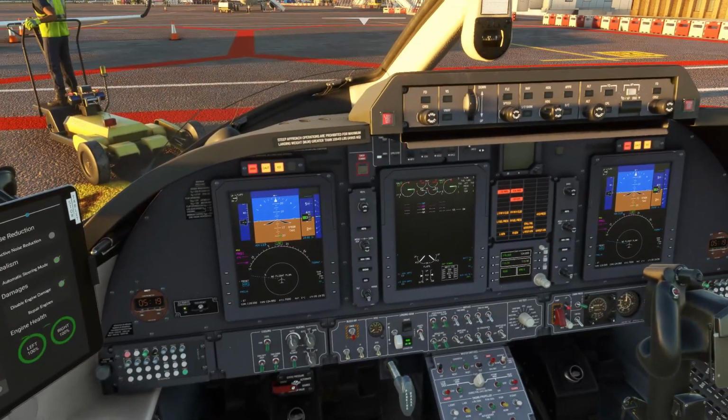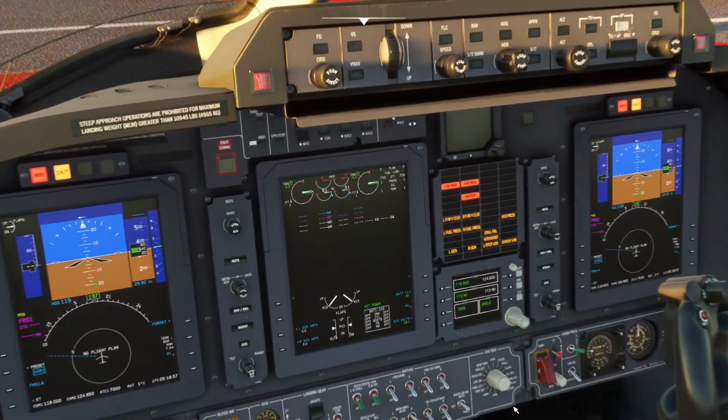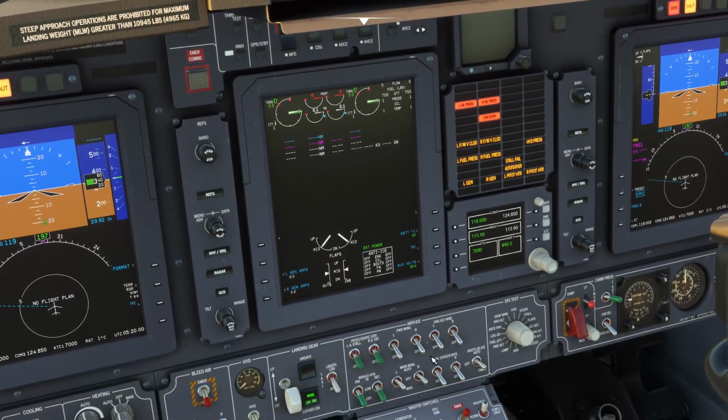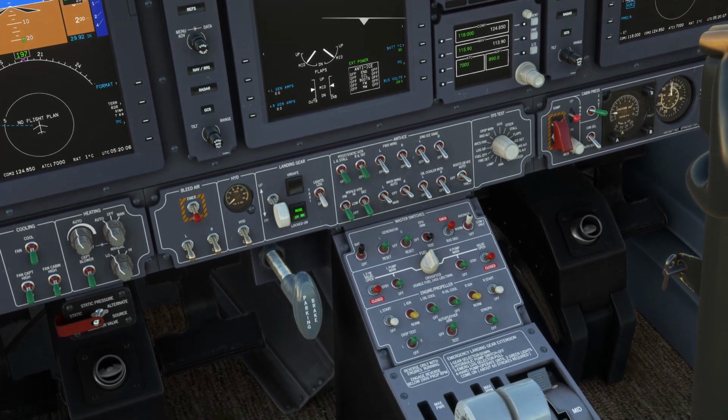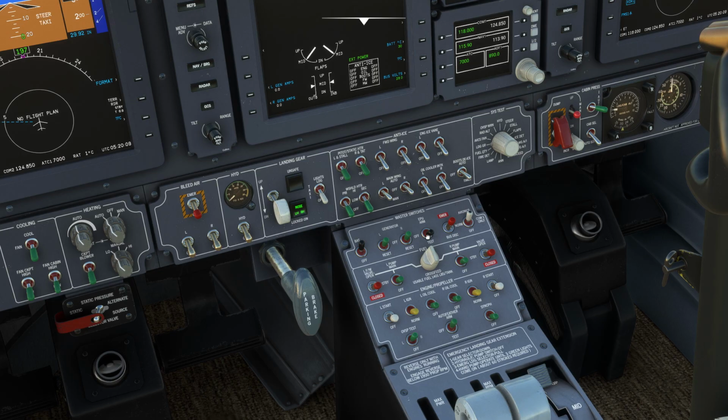Right, before engine start checklist, bus voltage, we checked that, it's 25, which is fine. Battery temperature is 30, which is okay. EPU switch. Now EPU switch is here, and you always move it to ARM. This is the emergency power unit, and the switch remains in ARM position whenever engines are running.